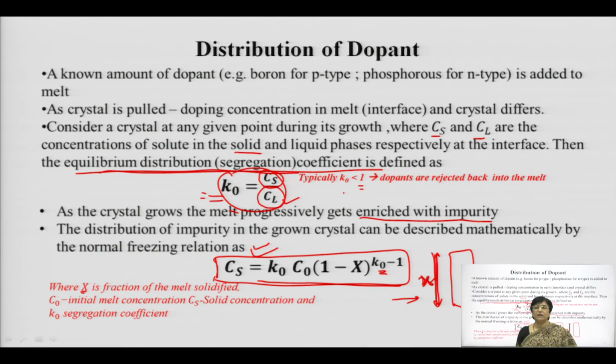So, this mathematics is giving you the idea of the rate at which the silicon ingot can be grown with the help of the seed crystal from the molten silicon, and within the molten silicon the ratio of impurities in the solid and in the liquid decides the segregation coefficient.